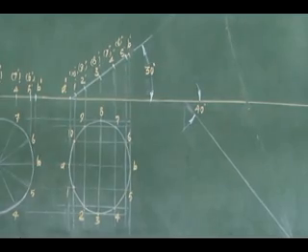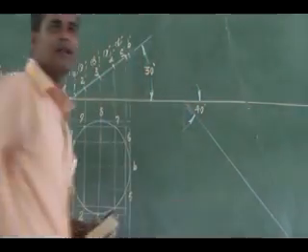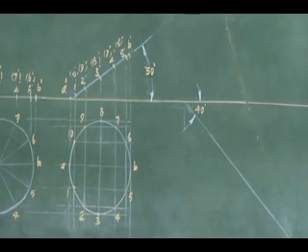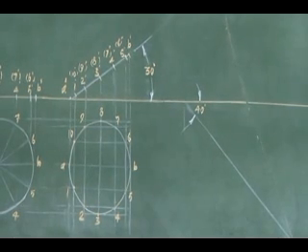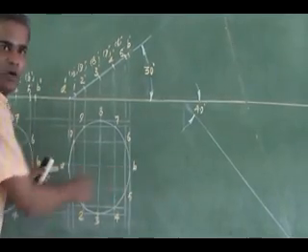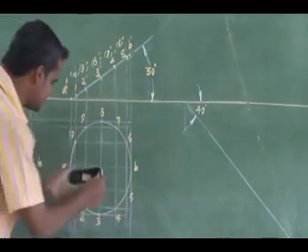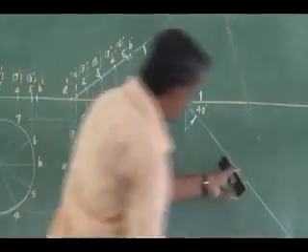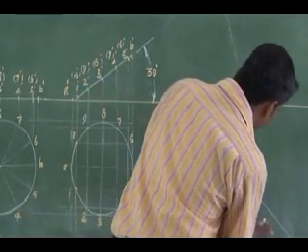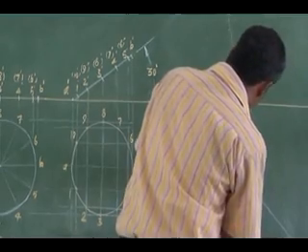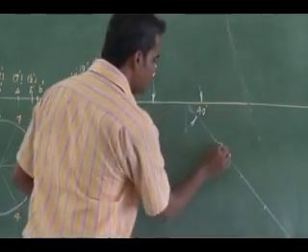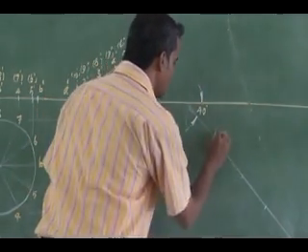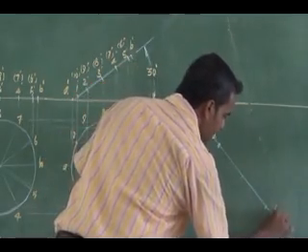You see here. So which one is going to be on this 40-degree line? First of all, AB. AB appears to be inclined 40 degree. So listen all of you. AB appears to be inclined 40 degree. So this AB, where I have in my top view, this is my AB. You measure this distance AB. Conveniently you mark it on this 40-degree line. So first of all, you mark this AB. This is my A. This is my B.